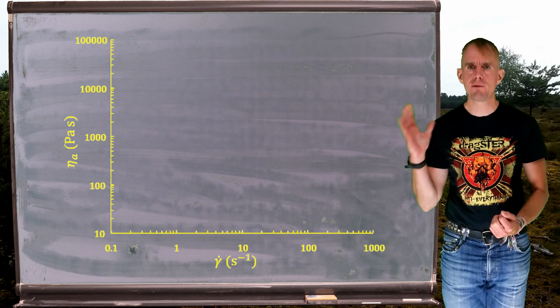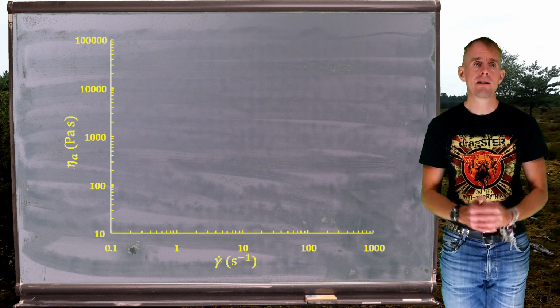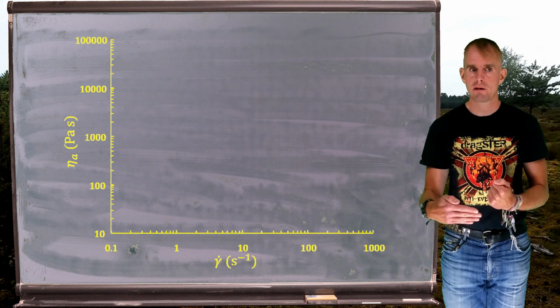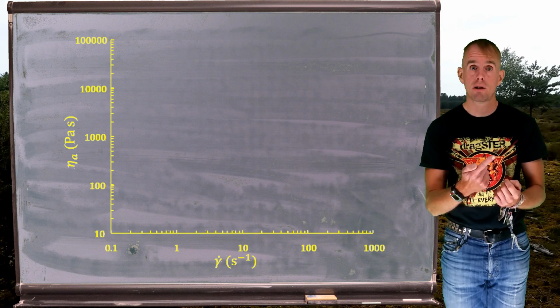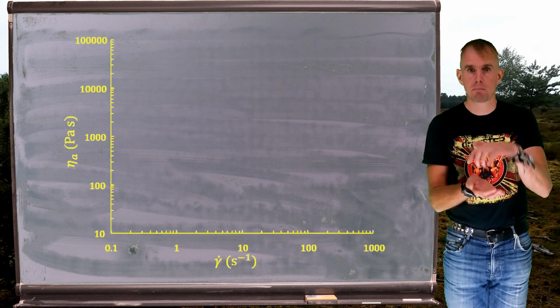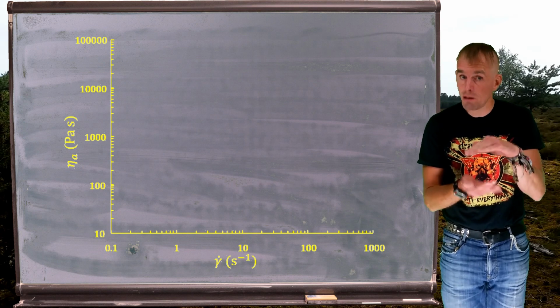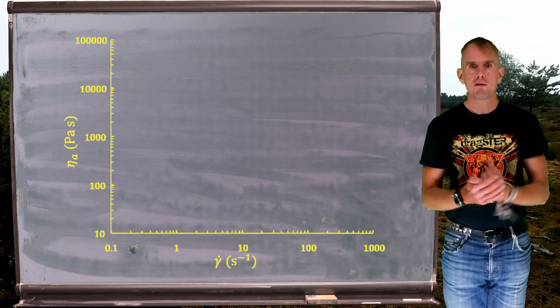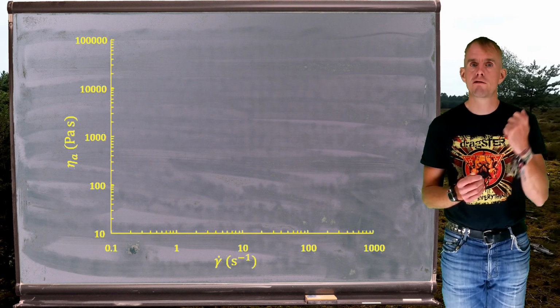What about real materials? What do we see experimentally? Well, I'm going to give you some examples now of a well-known sandwich spread, and I'm going to plot the data as apparent viscosity as a function of shear rate for steady shear experiments in a rotational rheometer. So parallel plate setup, fixed top plate, rotational bottom plate. I might have used roughened plates to eliminate the presence of slip.